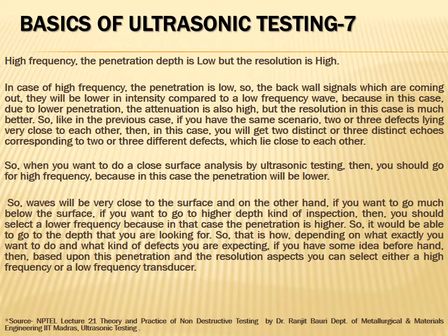For a high frequency, it is just the opposite of the previous case. The penetration is low, so the back wall signals coming out will be lower in intensity compared to a low frequency wave, because due to lower penetration the attenuation is also high. But the resolution is much better.